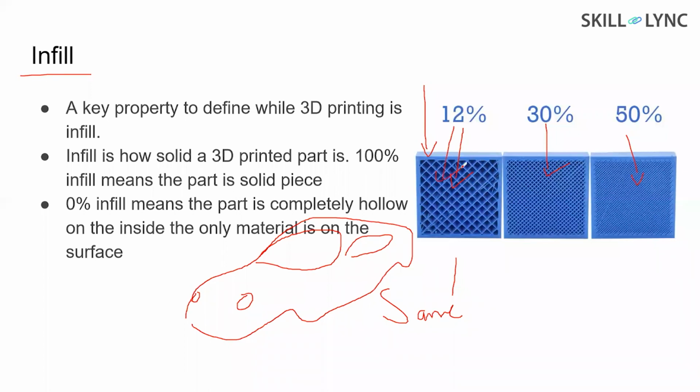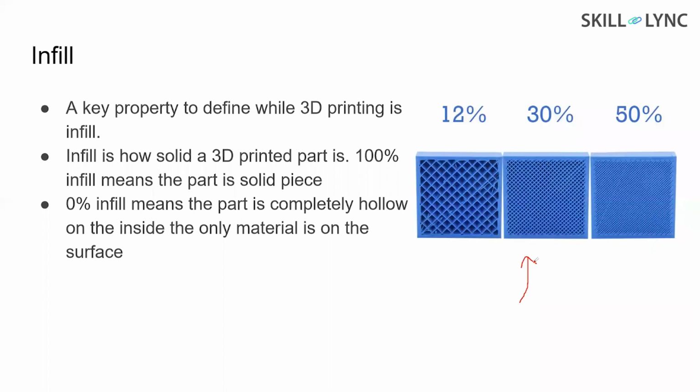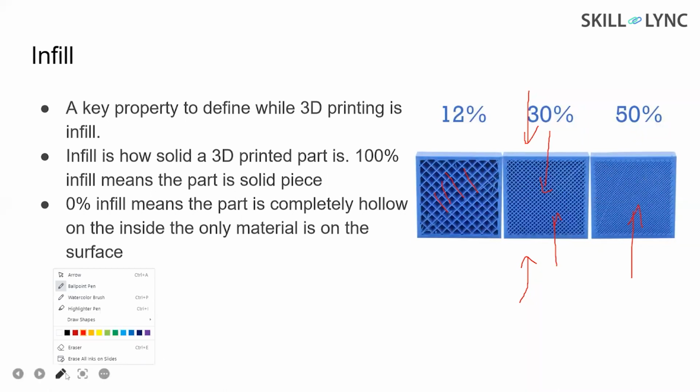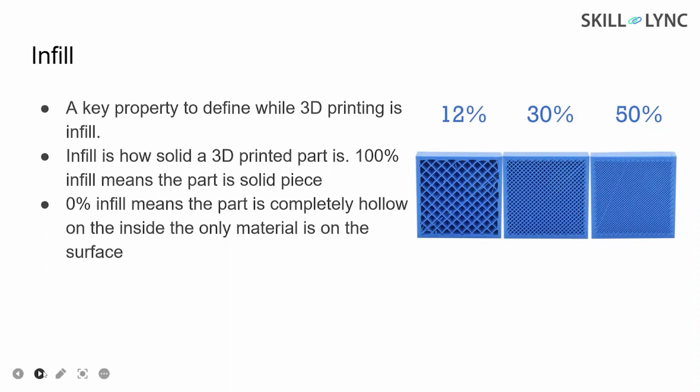Or when you want to make this hollow, in the case of filters and other stuff. But if you want to make your part for some function, your part should have some strength. In that particular case, you need to put in more infill, more ribs into the model. These are called ribs, right? You need to put in more ribs so that your part will be strengthened and it will withstand all the loads which are necessary. And if your part is fully for structural application, it should withstand a large amount of load, something similar to that. Then you can give infills from 50 to 100%. So what do I mean by 100% infill? There won't be these kinds of holes, right? It'll be completely filled up to the brim, solid. So this is your infill. Infill has a much bigger effect when you're designing structural components or functional components.